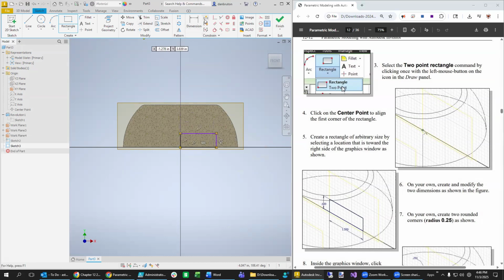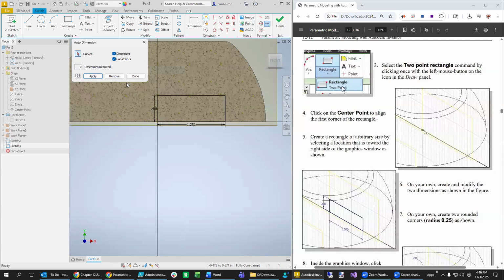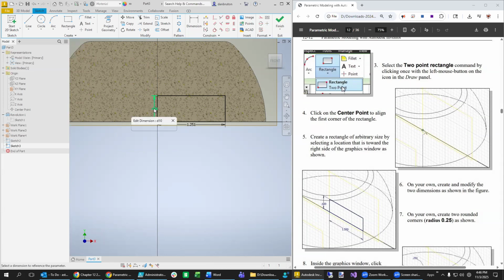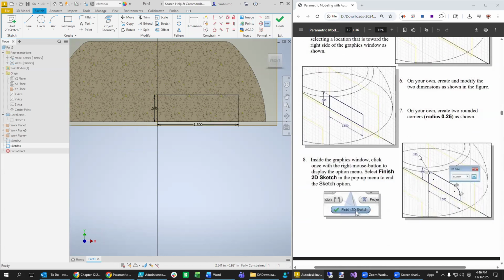You know what? We should try this thing here again. All right, that's not so bad. I mean, I'm not really sure how helpful it is, but you just double click on it, put 0.5, and then double click on that one and put 1.5. Maybe it's fewer clicks if we do it that way. Now we're going to put these rounded edges on there. So how about our fillets? Still defaulted to what I had previously put down. Like so, it is fully defined, which is nice.